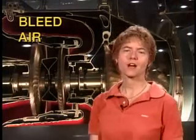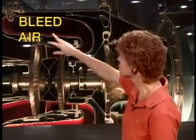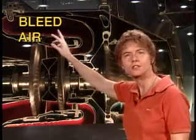Okay, the independent cabin air compressor like that is typically what you would find on a large piston engine aircraft to pressurize the aircraft. But if you're working with a jet aircraft, what you're typically going to be using is bleed air instead.